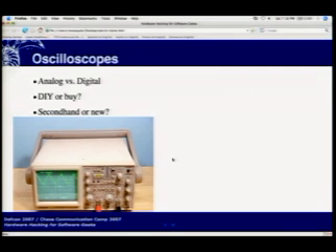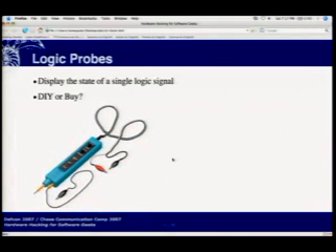Well, another alternative is to use USB-based oscilloscopes, but the display is not going to be anywhere near real-time, and there's usually going to be like a noticeable 3-4 second delay. Like if you're monitoring a serial port with it and you're trying to look at your frame size and you hit a button on your console and watch it go on the oscilloscope, it might be 3 seconds before you actually see it. But those USB instruments can be very useful because it'll only be a couple $100 rather than tens of thousands of dollars for the equivalent full instrument that you'd see in a lab.